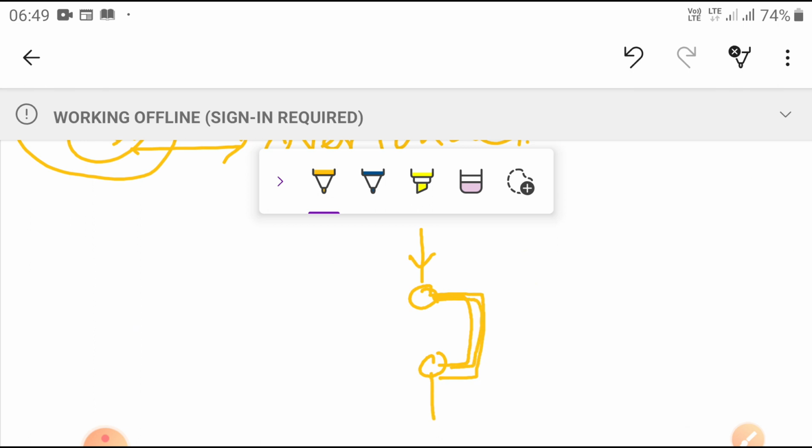Current is flowing here. Under normal condition, it will draw a current of, for example, I equals 10 amperes. The 10 amperes flows through this coil, and hence the bimetallic strip produces heat energy, and the temperature rises to, for example, 36 degrees. During the 36 degrees, the switch's two contacts are in closed condition.